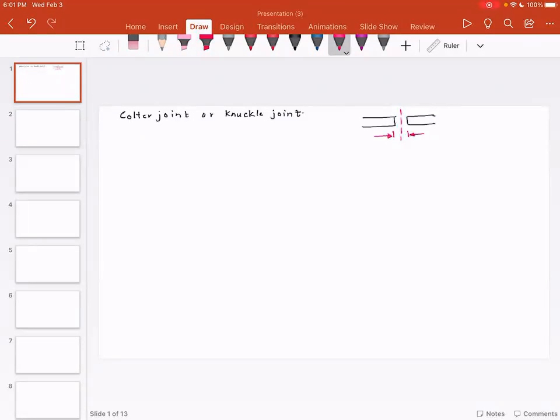So it is not difficult to visualize that you can have a cotter joint which could get unnecessarily stretched or compressed because of the distance between the two rods is not accurately maintained. So what is the solution? The solution is something called as turnbuckle. And most of you have seen this turnbuckle, and there are different ways this turnbuckle can be manufactured.